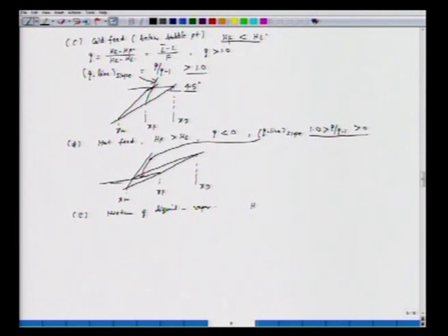So essentially we have HF less than Hg, but it's greater than HL. So we have a mixture of both vapor and liquid. The feed consists of, you can say, vapor and liquid. In this case, Q is greater than 0 and less than 1, and one can show that this Q line's slope will be nothing but LF, the amount of liquid in the feed, over LF minus F.